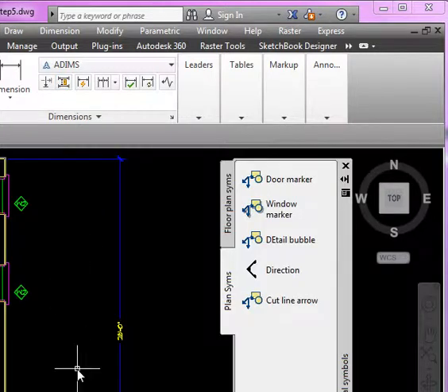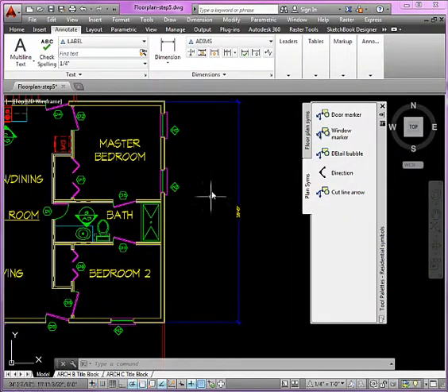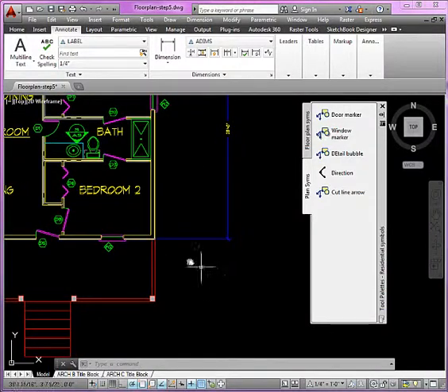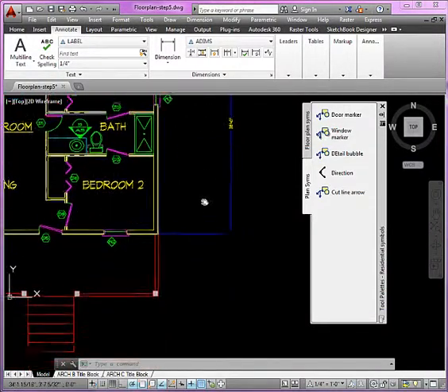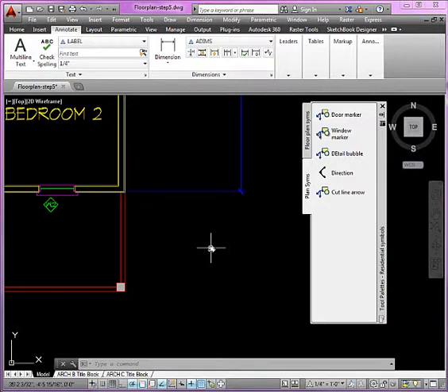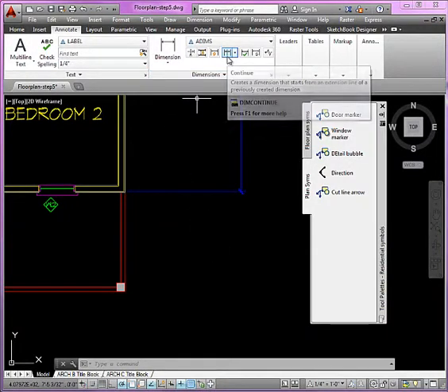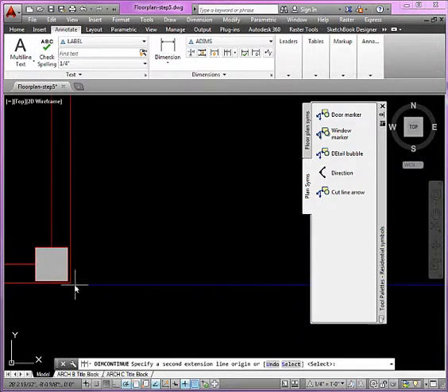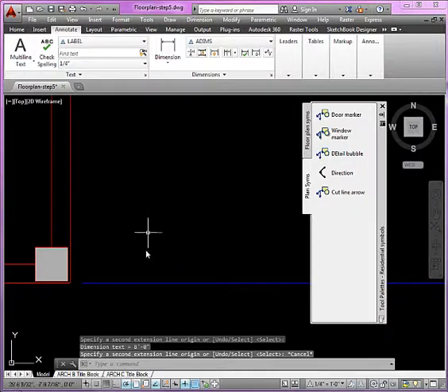All right. Right now, you can just lay them out. Think about this. Make the larger dimension further away from the model, and then you have your 2 other levels. So if I start like this, the next thing I want to do here is show that was the overall for the facade, but I still have my porch here, right? I can use a continue dimension to continue from that facade to the outside face of what would be the porch there, and then escape.